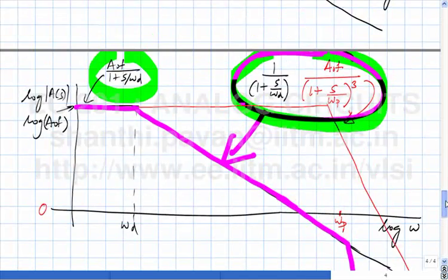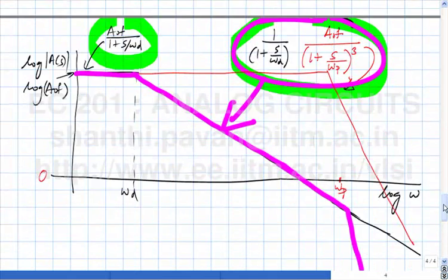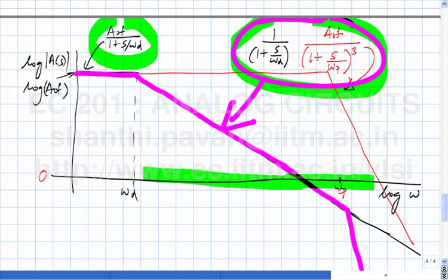So it's like this. Obviously nothing comes for free, because earlier the loop gain we had over this frequency range was much higher than what we have now. Correct? So all we have done is we have deliberately killed the bandwidth of the amplifier.